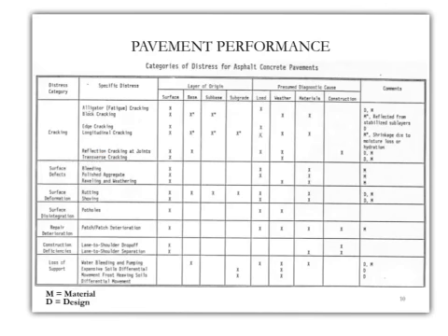Another example here is surface disintegration. Here we have the example of potholes, and all the way to loss of support. Specific distresses based on loss of support are water bleeding and pumping. We can also have expansive soils that eventually result in differential movements because of frost heaving soils, all the way to differential movements as a specific distress.